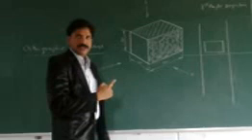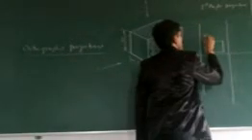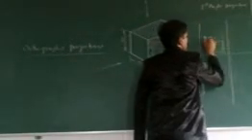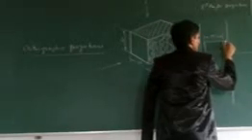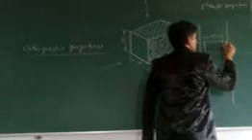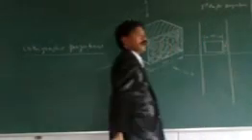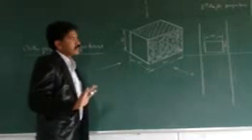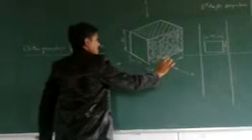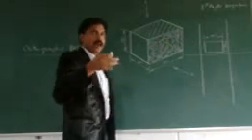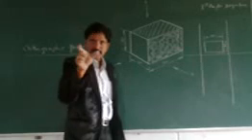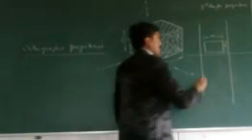Is the shape in the front direction a rectangle? So here, from here to here, the dimension is 100 and the height is 40. So this is 100 and this dimension is 40. Just to check now: in the front view, the length and the top view length are both the same. Am I right? Yes, sir. So simply, on the basis of the front view, project the length dimensions towards below the x line.